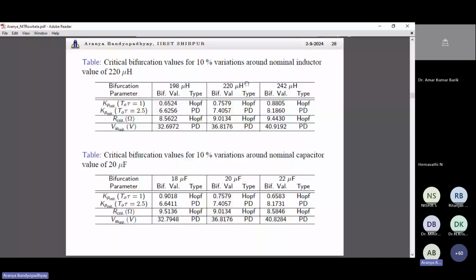Even if you are dealing with an E type of core, you can play with the air gap. You can insert some paper or dielectric or insulating material, and then play with the air gap of the inductor and try to make the value, in the experimental case, as close as possible to the nominal value which you have used for the analytical case. But it would hardly be exactly the same.